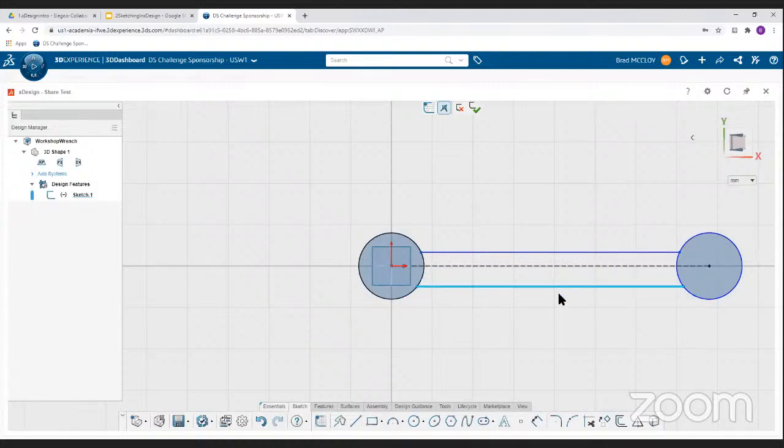But we kind of want them to be centered. And that's where the center line comes into play, and another constraint. So if I click this line, I click that line and this line. So I've got the two lines and the construction line. Again, when I'm done clicking, the dialog comes up with our new relations or constraints.